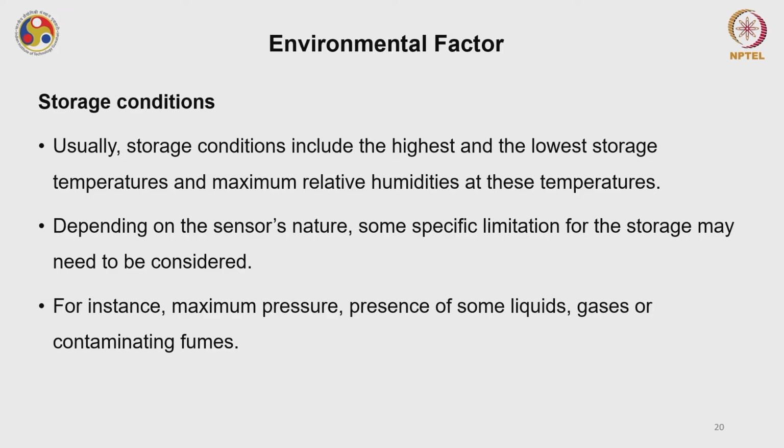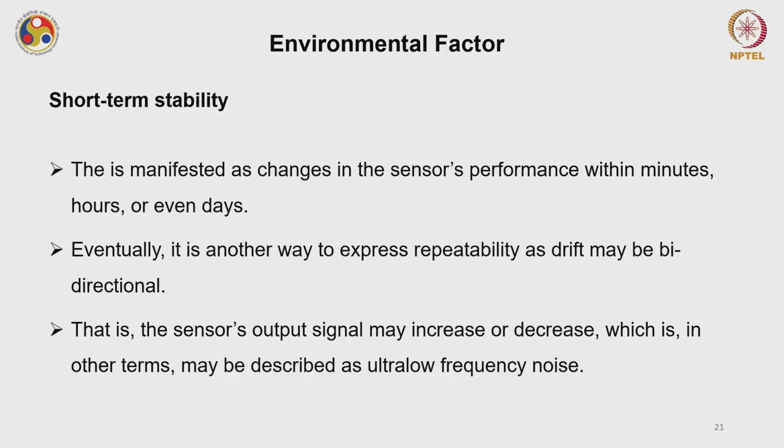Depending on the sensor's nature, some specific limitations for storage may need to be considered. For instance, maximum pressure, presence of some liquids, gases, or contaminating fumes which may hamper the sensor's performance. These environmental factors or storage conditions may affect the short-term and long-term stability of the device.